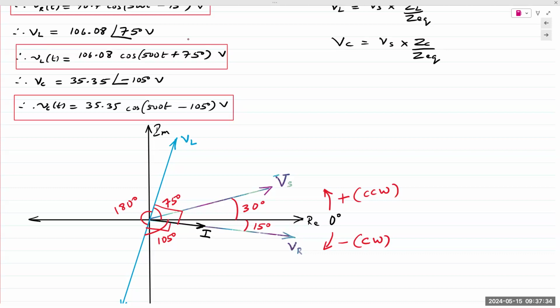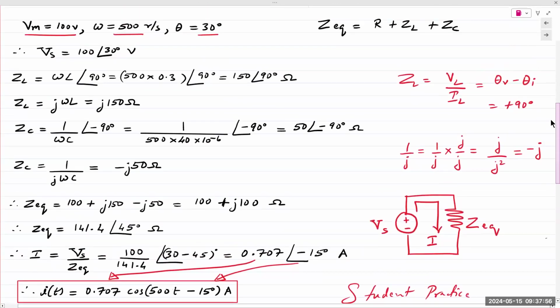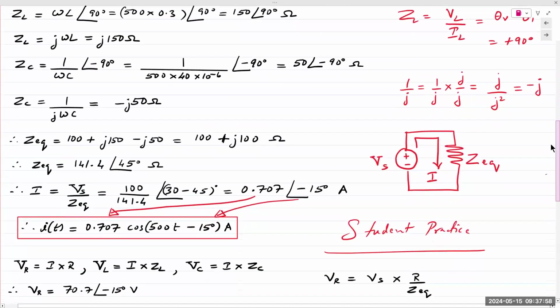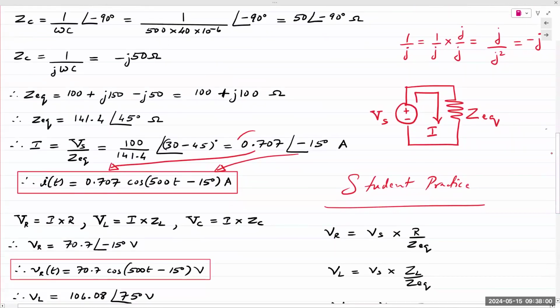Whatever the angle is, the approach is straightforward. It's a vector. You find the angle. Once you have the angle, just draw an arrow at that angle, mark and note the quantities, and that's it. It doesn't have to be to scale. These are not to scale. I is only 2. The magnitude of I is very, very small. It's not even 2. It's like 0.707. The magnitude of the current is 0.707.